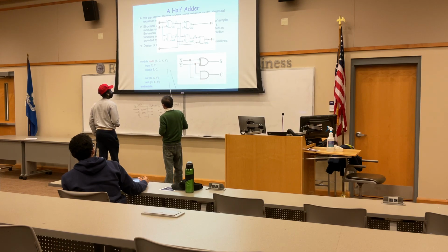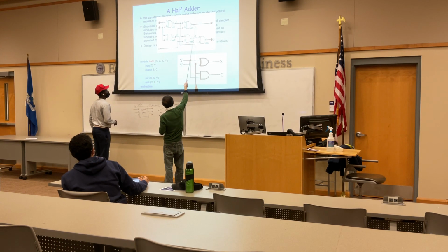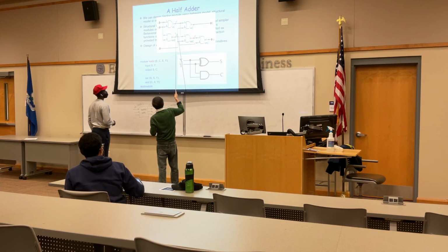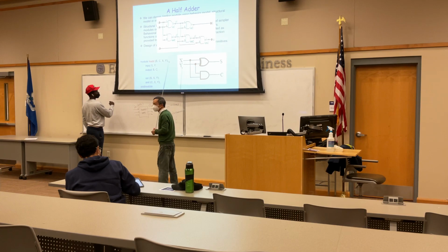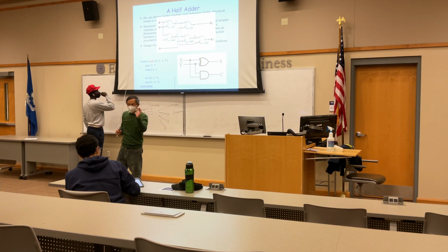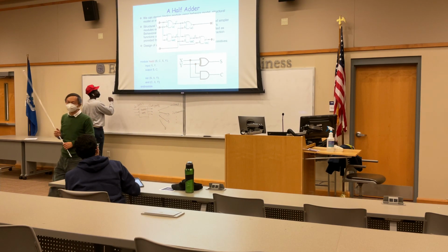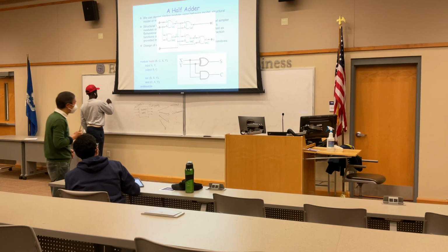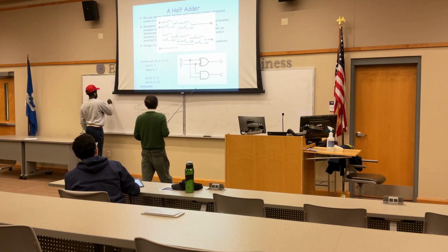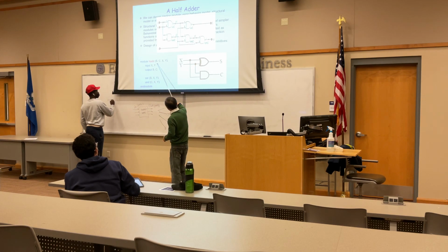And then define the signals, and then what gates are there. We have internal wires, we call them wire N1, N2, N3. And then you call XOR gate, NAND gate, XOR gate, NAND gate, and specify their connections with the same order you defined before, output then input. This is the example we showed you.